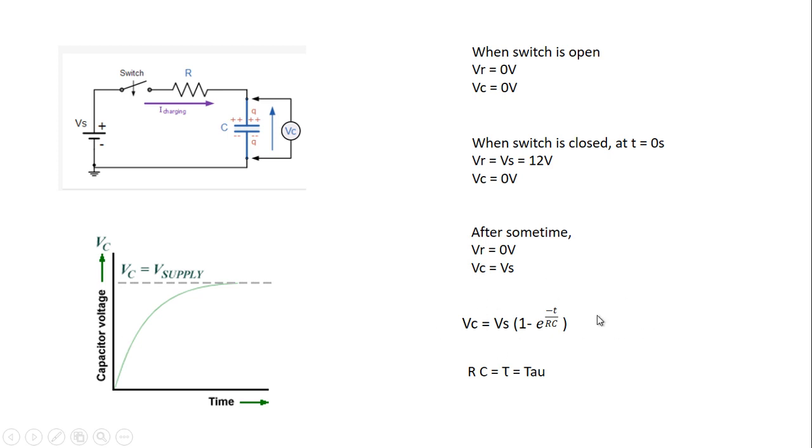And now from this equation it is visible that when it gets fully charged, Vc is equal to Vs. That means we must know the value at the point when this thing becomes equal to 1, or Vc is equal to 100% of Vs. To make this, we must know the value of RC. That means this RC is really important.